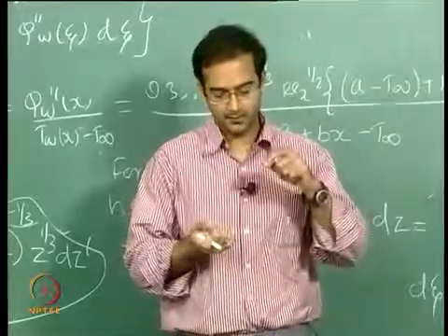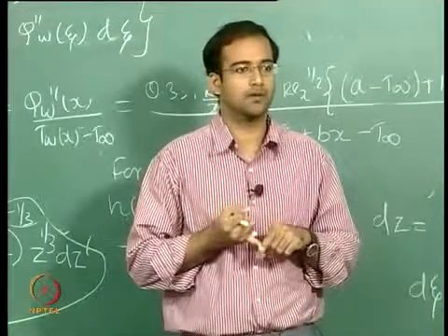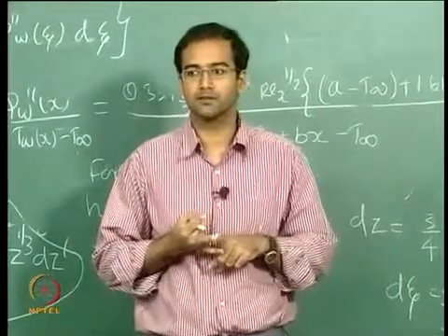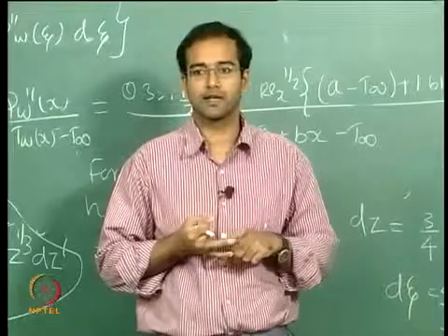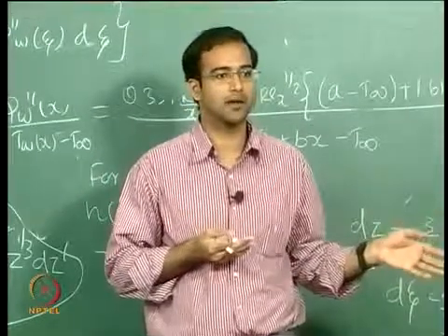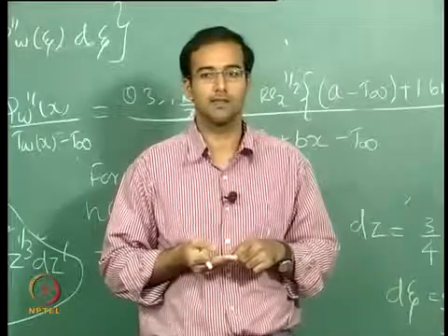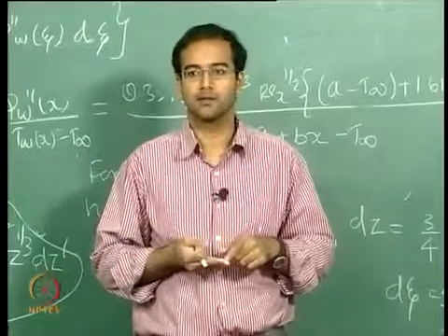Like we have seen, if you have the Falkner-Skan solutions for the wedge problem, you have the similar Karman-Pohlhausen solution when you use the integral methods. Of course, like the Blasius solution, there you can approximate some velocity profile and very easily find the expression for, say, the local Nusselt number.